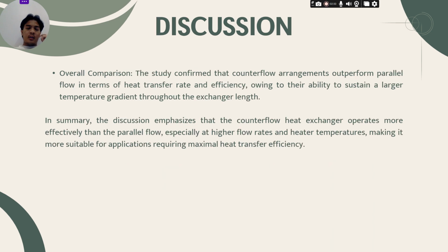The last one is overall comparison. The study confirmed that counterflow arrangements outperform parallel flow in terms of heat transfer rate and efficiency, owing to their ability to sustain a larger temperature gradient throughout the exchanger length. In summary, the discussion emphasizes that the counterflow heat exchanger operates more effectively than the parallel flow, especially at higher flow rates and heater temperatures, making it more suitable for applications requiring maximal heat transfer efficiency.